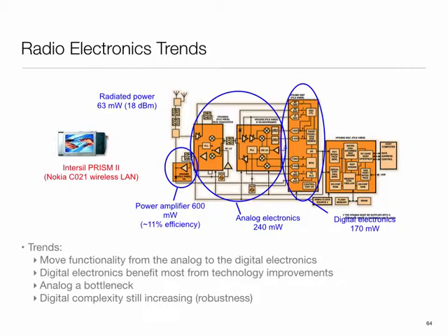Let's say it was a pulse modulation scheme. By the way, this holds true for frequency also. In fact, the reason FM radio is better is that even if the amplitude and all are corrupted, I can still extract the information. That's why FM radio is cleaner. It doesn't carry information in the amplitude or the envelope of the signal.